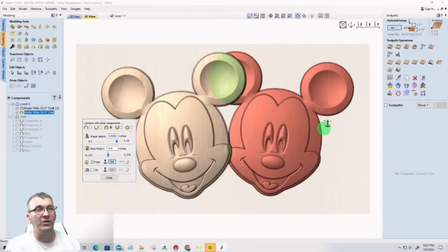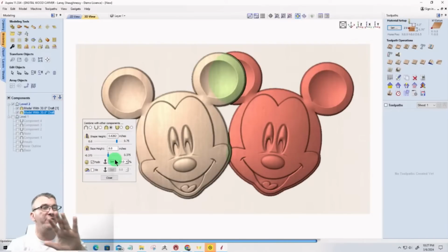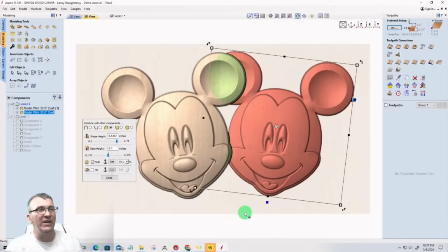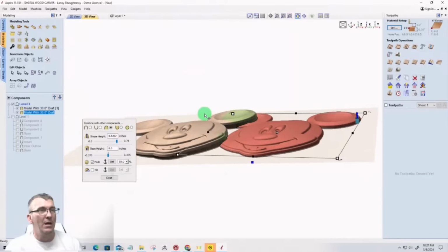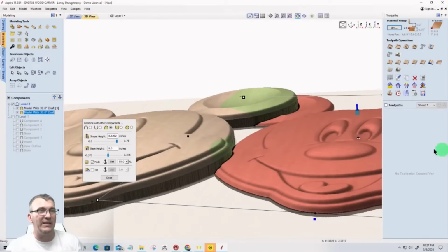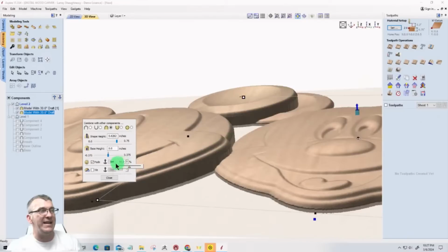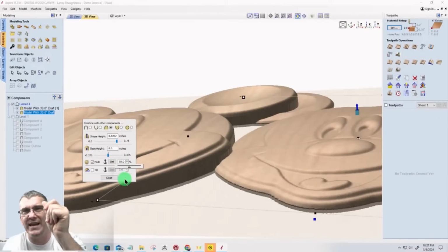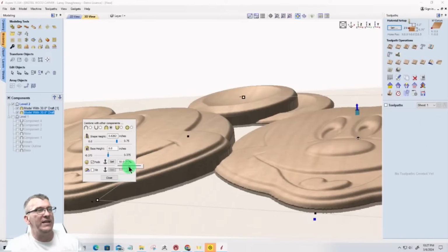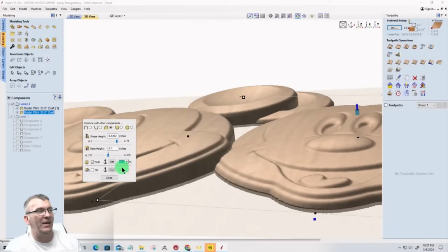So if I come over to the right side here and I click once, and I come over to the left side and I click the second time, when I fade this model, it fades. You can see it's kind of almost like that tilt down, John. I don't know if you can see that on the screen, but it's fading down. Now I'm going to turn the fade. By default, as soon as you fade, it's 50%, right? I don't need 50% of fade, but I'm going to bring that down to, let's say, 18%.